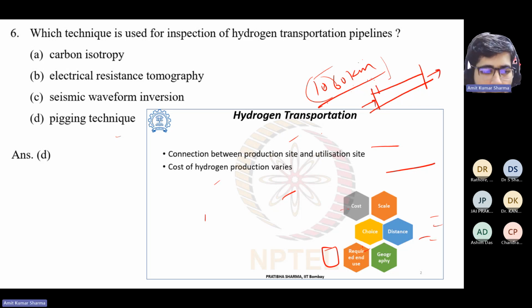The software that I was talking about basically works on the pressure. It senses pressure through the pipeline. If there is a sudden and uneven pressure drop, then it detects that there will be some leak. Because if your fluid is flowing through a pipeline, then the pressure drop should be as per the elevation, the friction, and all those things only. You will not see a sudden pressure drop.